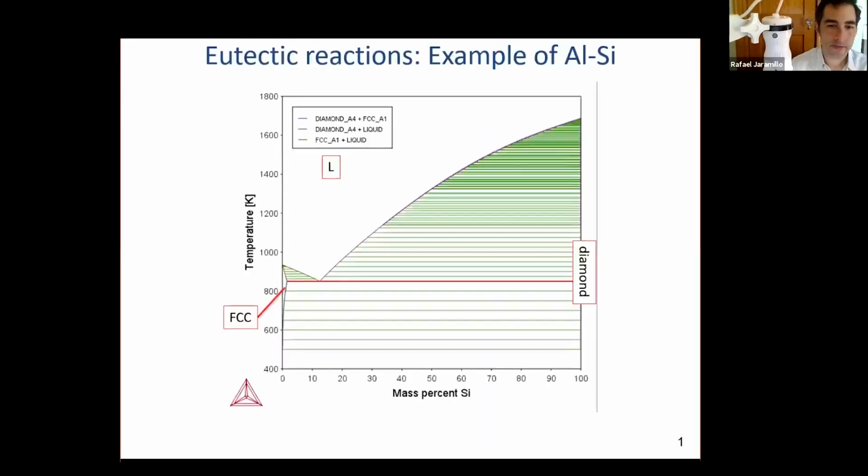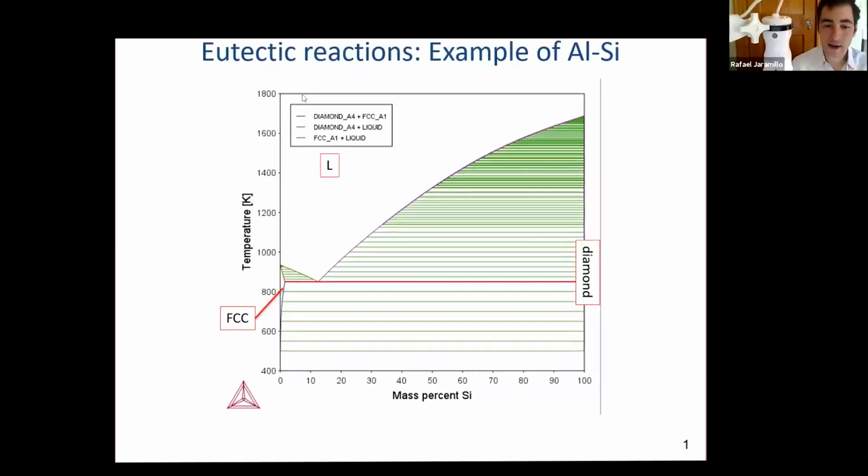Okay, so here is aluminum silicon. This is a eutectic phase diagram. This is a very typical sort of geometry. Your eye will pick out eutectics right away because eutectics have this gull wing shape. This purple line here that I'm laser pointing out is the liquidus. It is the locus of points above which only liquid phase is stable. And in a eutectic system, you have a local minimum to that. It's also known as melting point suppression. So right there is the eutectic point.